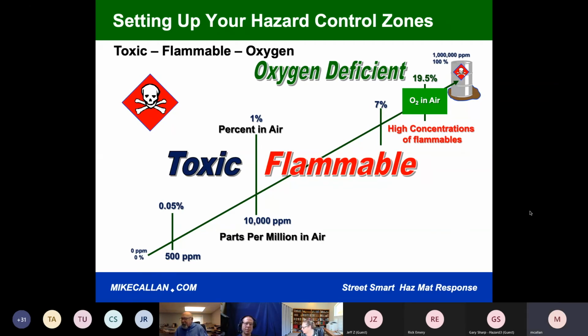I know they like their meters and they grab their meters. So one of the things about meters is, let's look at toluene. If you look at my 1%, and this is why I like to use toluene in this example, 1.3% of toluene is 10% of the LEL. Or, excuse me, its lower explosive limit is 1.3%. So the flammable range is right about what you're looking at, because the flammable range of toluene is 1.3 to 7%.